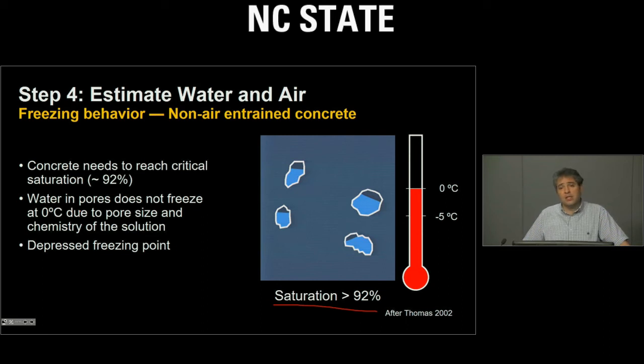However, ice does not form in concrete at 0 degrees C. This is because we have a lot of salts inside the concrete. Concrete pore solution is really very similar to saturated calcium hydroxide, so it does not freeze at 0, and there are other effects due to the size of the pores inside the concrete.